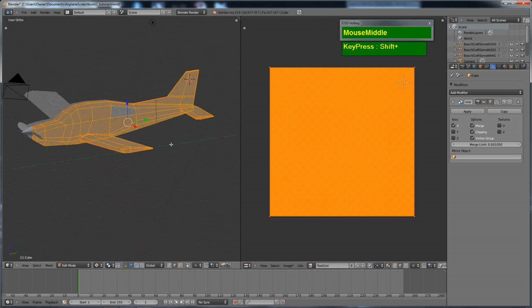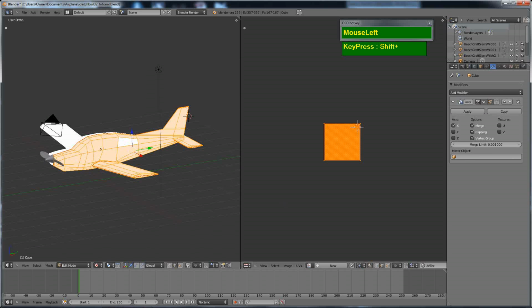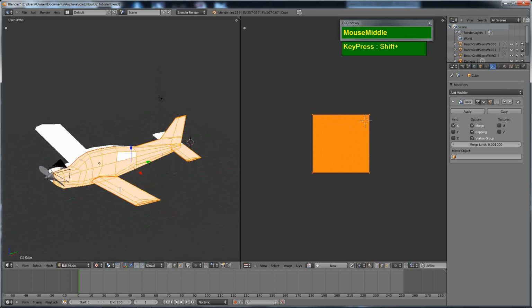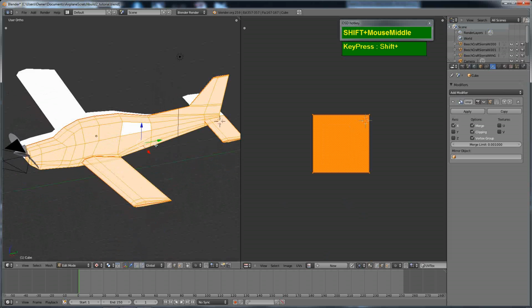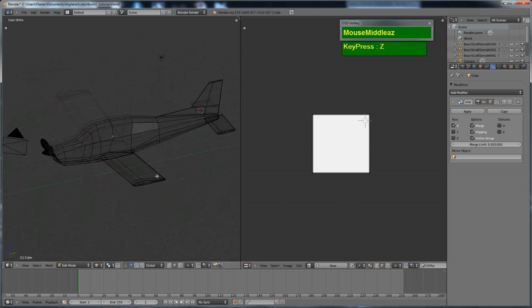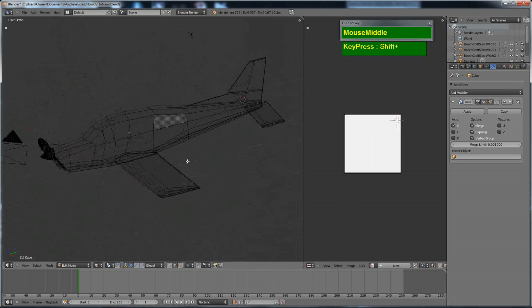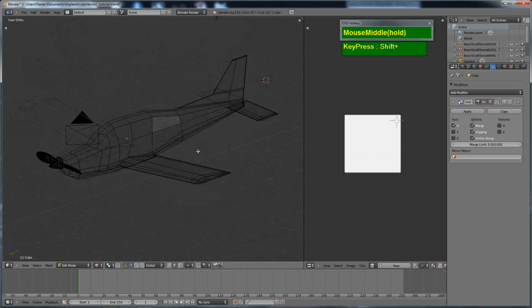Now I'm going to get rid of this test grid by clicking on the X pattern here. So now everything turns white because nothing is being assigned right now. And I'm going to get rid of the seams by pressing Ctrl E and then Clear Seam. This is the stage where you should start off with, so there shouldn't be any seams on your model.